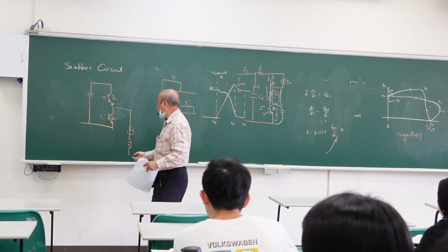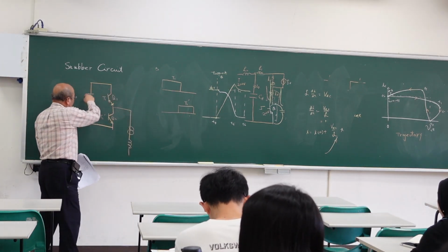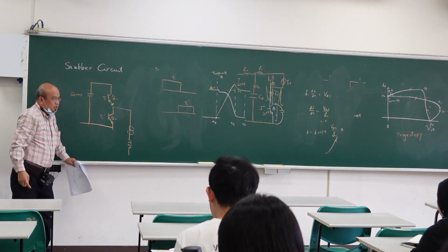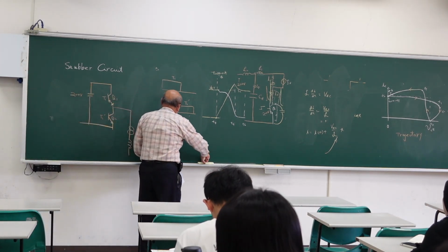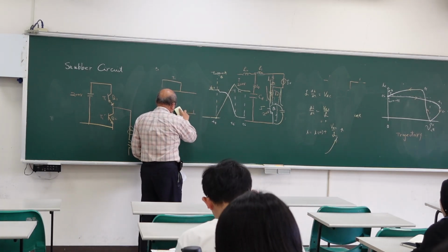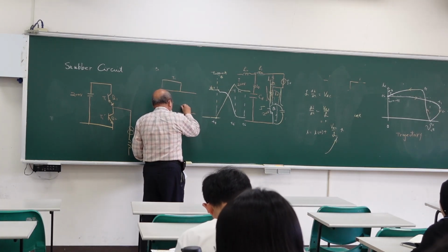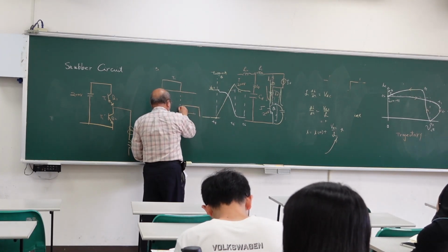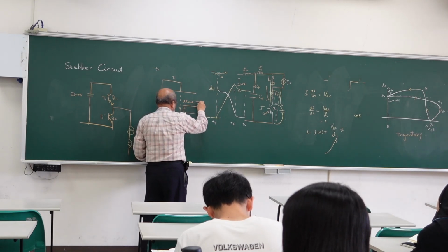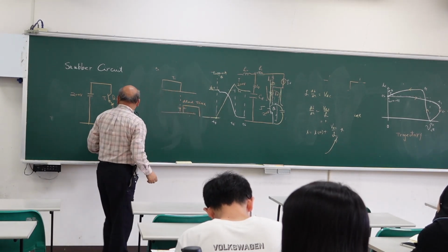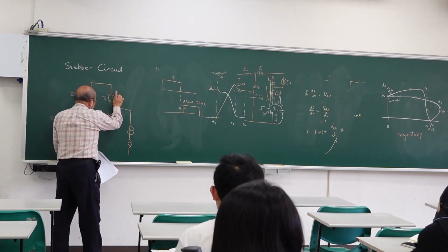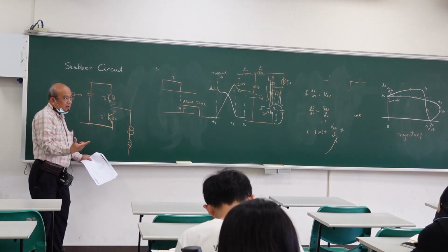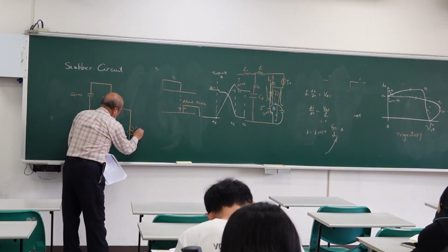If you turn on T1 and T1 plus together, then what happens? Short circuit. So we have 200 volt short circuit. So you have to make sure after T1 turns off, you can turn on T1 plus. So you have to keep this way. So you have dead time here. But during the dead time, T1 is turned off, T1 plus is not turned on yet.